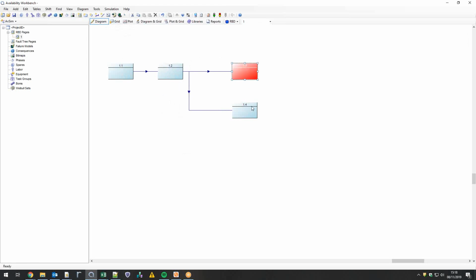With regards to a parallel arrangement that could represent a set of dormant systems, perhaps this section of the plant requires and has 2 pumps, one of which is in standby, we need a single output for this. We can do this with what we call nodes. We can add a node to the diagram by simply clicking as we've done with the blocks, clearing the add mode, and then reconnecting the final connections. Objects within the diagram can be simply moved by selecting them and using the move icon, move cursor, to move it to where we want in the diagram.